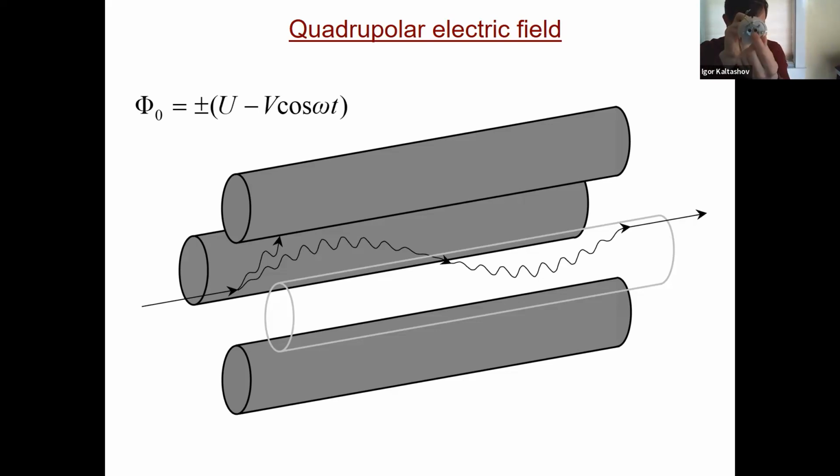Here you see only 3 quadrupole rods. One of them is removed here. On this end, you have all 4 of them. Okay, and this is how they are arranged. So it really is about 10-15 centimeters long, and each of them is less than 1 centimeter in diameter. So that's the arrangement. Very, very small and very easy to manufacture.